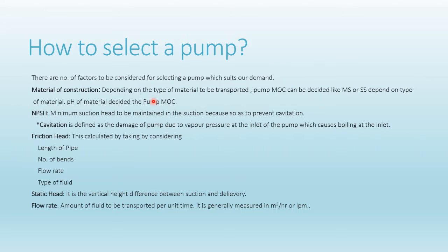See, type of material to be transferred. If you are transferring less corrosive material or higher corrosive material, the pipe strength and the pipe corrosion resistance, and the pump internal material corrosion resistance also should be more to withstand the corrosion of the material. So generally we will be considering the pH of the material to decide the pump MOC.